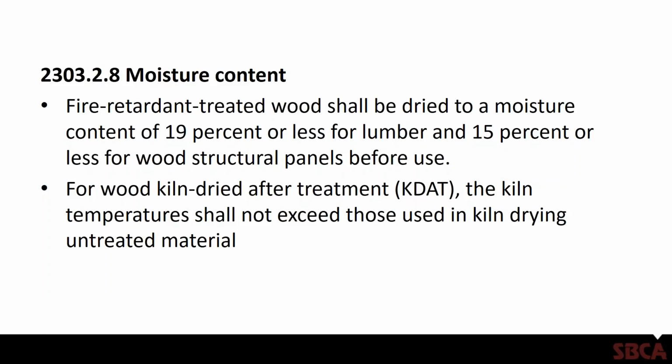Many of these are water-based, or I believe they're all water-based, and so then the product has to be redried down to what's considered a dry use application, or dry use moisture content, which for lumber is 19% or less. For kiln dried after treatment, KDAT, the kiln temperatures cannot exceed the kiln temperatures that would be used for untreated material.